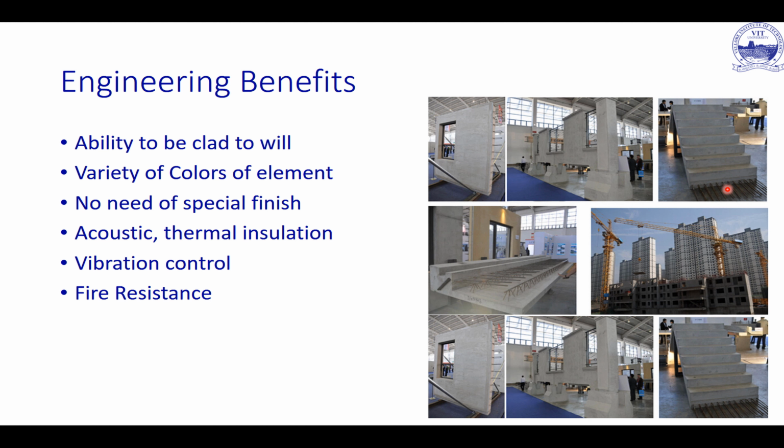Again, you can get whatever required acoustic performance or thermal insulation, and also vibration control. Vibration is based on the stiffness of the entire structure, so you can modify the stiffness by using post-tensioning or something, and you'll find that the vibration is also much lesser. When you are saying fire resistant, it's much more fire resistant than steel. Basically, that's the only thing where we can really look at it.